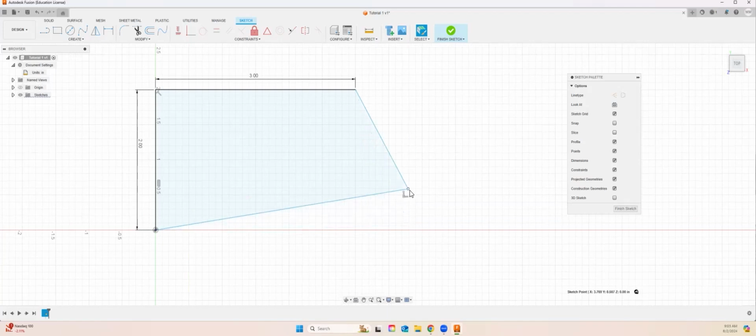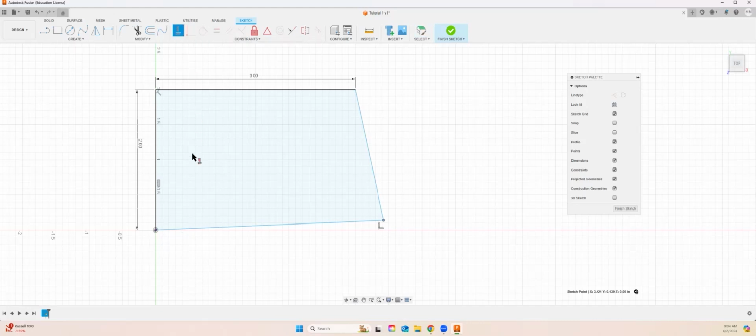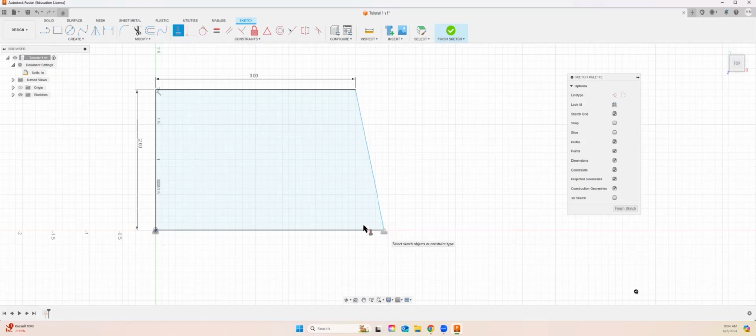So let's say you're playing like, oh, I moved it, and I don't want that. I forgot the dimension. So this is what you want to fully constrain, right? So once again, I'm gonna click this point. I'm gonna click this constraint horizontal vertical. So that point, then this point in the center, and there we go. Now you can see this symbol over here in the bottom. That's a horizontal. That's the symbol of the constraint. So we have that one now.